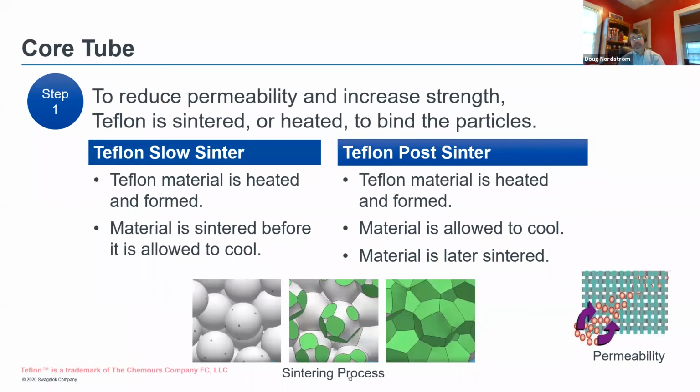Moving on now to the Teflon, a little more detail on permeability. I think most people probably know, but permeability is gas molecules flowing through Teflon. There's holes in the Teflon when it's extruded, and gas molecules just flow right through the Teflon. We did some testing with a standard Teflon core 1 foot hose. At 3,000 psi, it permeates about 2 liters per hour at just a 1 foot hose.